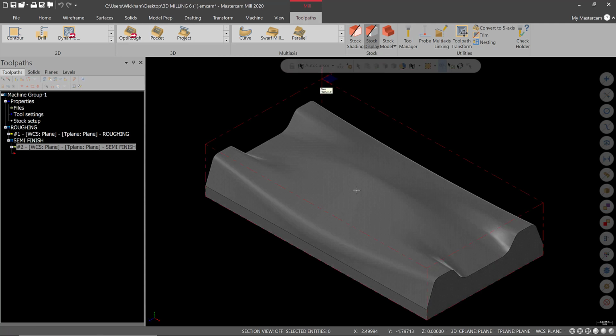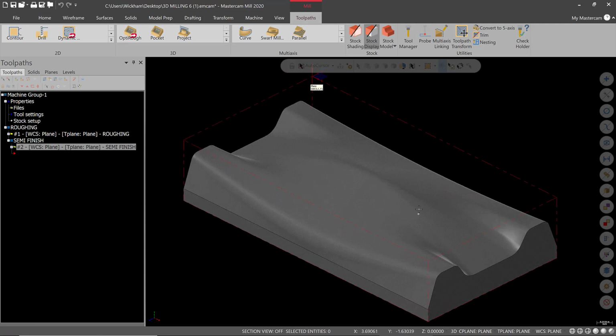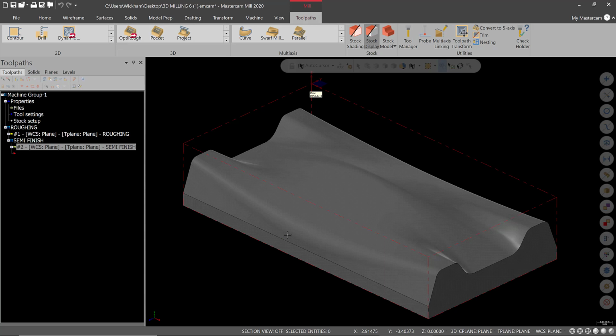All right, don't worry about it for this one. I'm focusing on the 3D machining. Again, that looks a lot worse on Mastercam than it would on the machine, depending how accurately you locate. It may not be the best option for you to locate in the upper left corner. Let's say that you're not really worried about the left and right. That's just out there, but you're really worried about this transition. Maybe you want to pick up the center. All right, sweep an indicator, pick up the center to make sure you're on center of the existing stock.